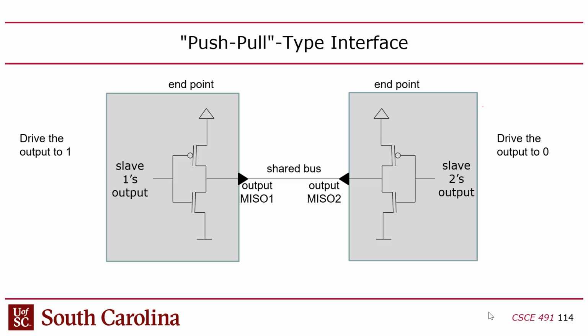And then if I want to do the opposite, I can pull this wire down to ground by turning on the NMOS here at the bottom and then turning off the PMOS, which disengages it from the VDD and shorts it to ground, right? So basically you're pulling up or pulling down, and you have a PMOS and an NMOS whose gates are shorted to the input.